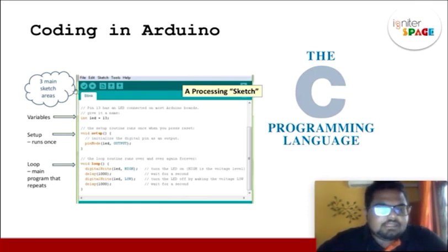You can see the Arduino software, which we call Sketch over here, and there are three main areas in the sketch. In a sketch, you have the declaration section where we put the variables like the LED pin number. Then we have the void setup function. The void setup runs when you turn on the Arduino the first time, or you load the program the first time. Whatever is inside the void setup will run. I'll explain what is inside here later. Then we have the void loop.